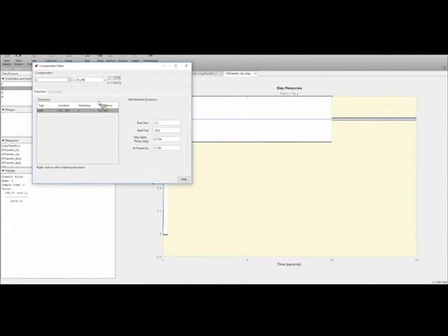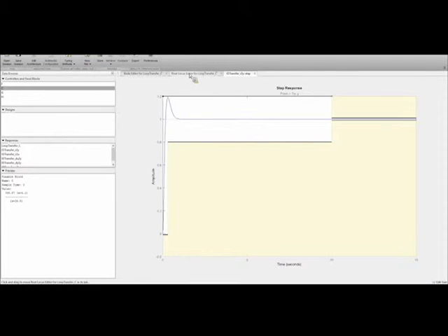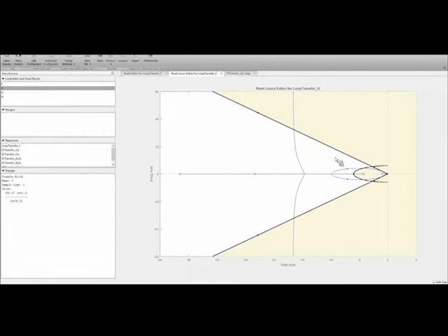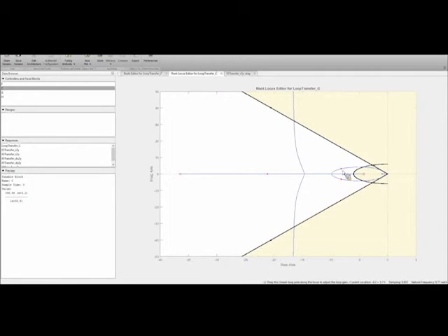All right. The other thing, sorry, thanks for the pause too. I forgot I was going to show you this. This tool is nice because if I want to look at different gains, I can just move around these pink dots, right? And it changes the pole location. So I can just drag them along the root locus. The other thing is that you can change your design. The plant is fixed, right? It's coming from the idea that that's usually hardware, that doesn't move very easily.